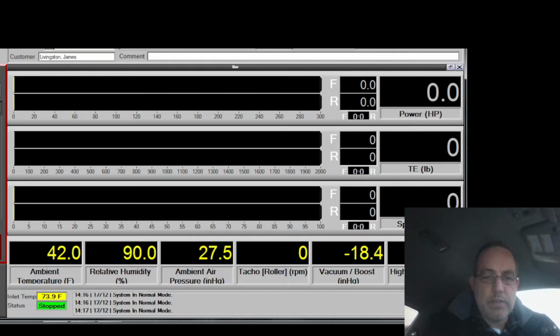I apparently have a slight reaction to what I ate for lunch. So my VE is showing 57, 58, but I'm showing 12% too much fuel. And 57 is definitely not 12% too high for one of these cars at idle, so I don't think it's that. This has got 13.